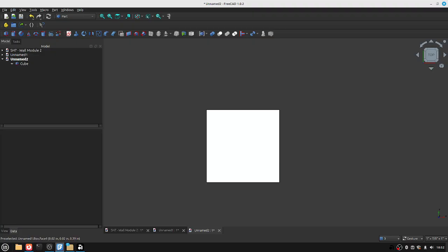I've never done this, but you change the properties in here to turn that into your base plate by creating a cube that's a solid like this, that's 1.5 high, 5.5 wide, and then 48 inches long. So that's another approach. But that's it. If you do this, then you've got everything.